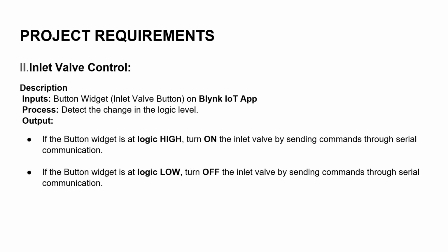The control of the inlet valve. The inlet valve can be operated through a button on the Blynk app. When the button is high, the inlet valve opens to fill the tank. When the logic is low, it closes automatically. This helps in preventing overflow and reduces manual effort.